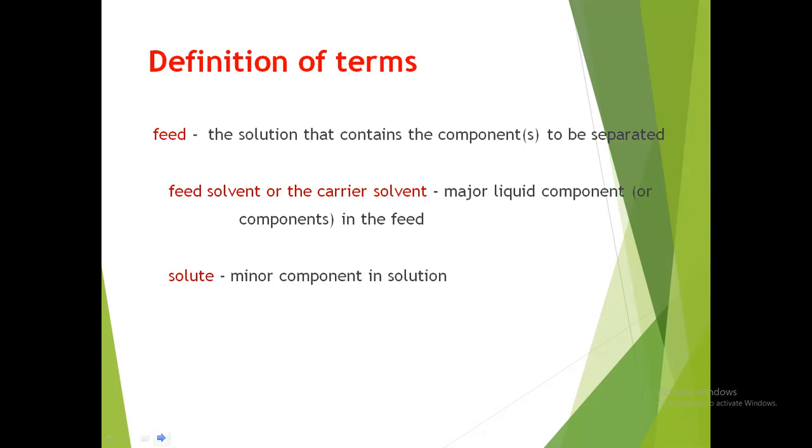So when we speak of solvent extraction, we take out a component from a feed using a solvent, which will be responsible for separating that component from the rest of the mixture in the feed. The separated component goes to the extract. The other components are in the raffinate. Of course, just like in any process, we don't expect a 100% separation. But in this case, liquid extraction is an option that is less costly than the distillation process or the highly costly version, which is the high vacuum distillation process. It is less costly because we can actually recycle the solvent that is being used.